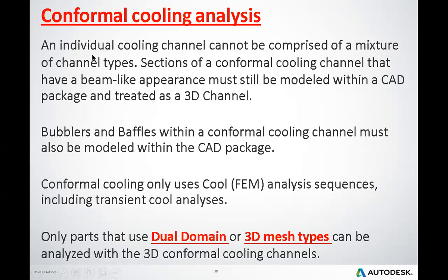More in detail, an individual cooling channel cannot be comprised of a mixture of channel types. So a section of a conformal cooling channel that has a beam-like appearance must still be modeled within a CAD package and treated as a traditional one. Bubblers and baffles with a conformal cooling channel must also be modeled within the CAD package. So we have to model in the CAD package first. And conformal cooling only uses Cool FEM analysis sequences, including transient cool analysis.